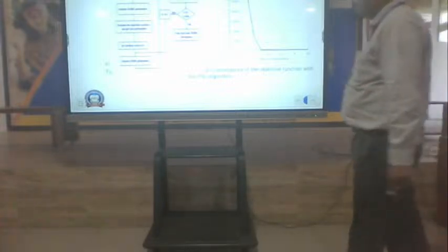So based upon the requirement of our system, if I want the electrical vehicle to go fast, I will reduce the rise time. That means I want to increase the KP value. Similarly, if I want our electrical vehicle to have zero steady state error, I have to give more focus to the integral controller. Like that, based upon our actual real time requirement, I will adjust this KP, KI, KD, lower bound and upper bound.